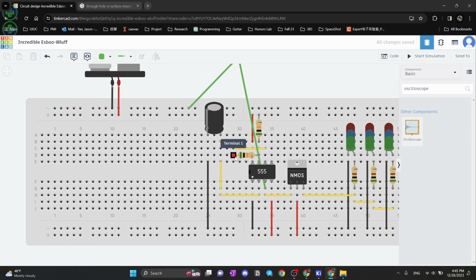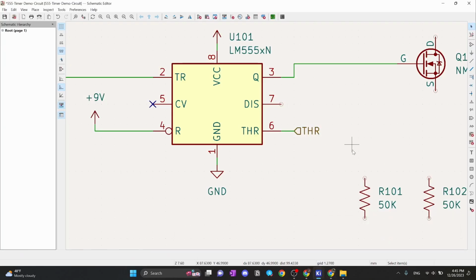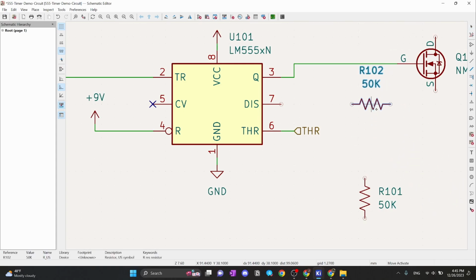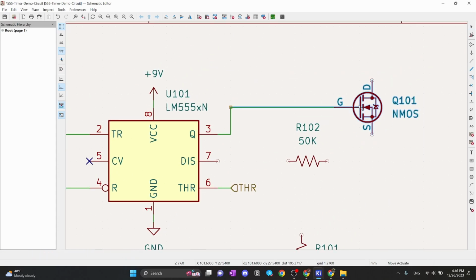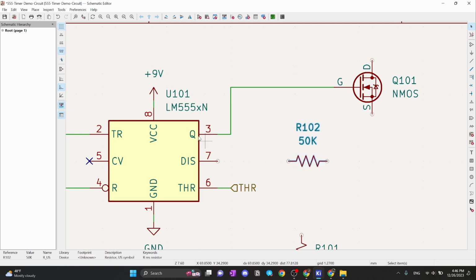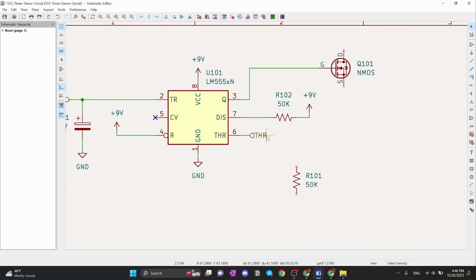And pin 7, as we mentioned, has a pull-up resistor that's connected to power, and another resistor that goes to pin 6. To do that, we can have one of those resistors, let's say this one, here, and we can move everything here, just above a little bit. Again, copy another 9-volt here, and connect them. Connect that back to pin 7. Move them a little bit closer. And we want a resistor to pin 6, and so we can just move this label down a little bit.